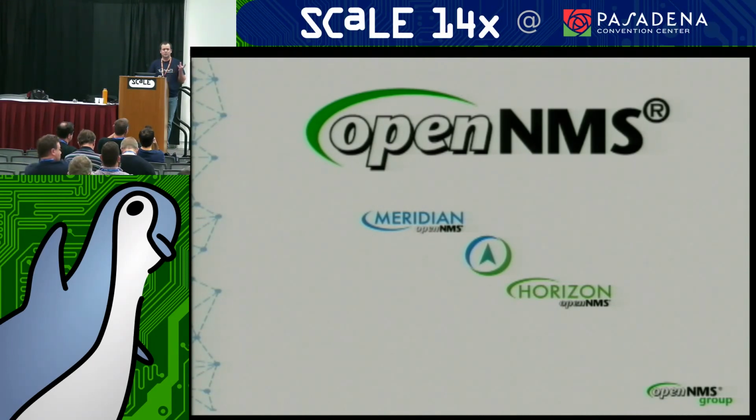I think the one I ended up with needed 4.5 or 5 volts. There was some number up in there where I ended up using 4 AA rechargeables. Those didn't quite last 24 hours set up as a web server. So what you really want to do for this is do the deep sleep and do a push collection. I wanted to keep the presentation simple, so I wanted to present this. But that's going to be the next iteration, is developing a push model that's collectible and then presenting that as like the low power usage.